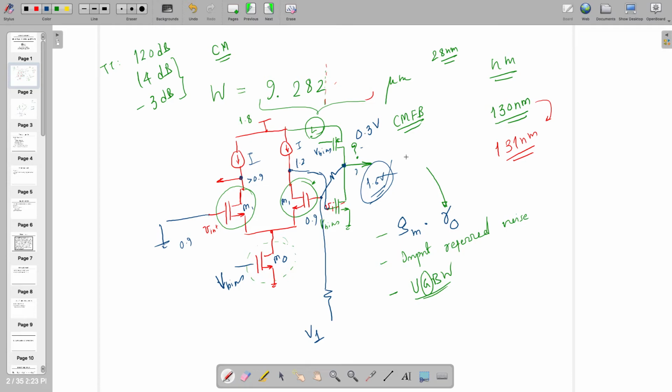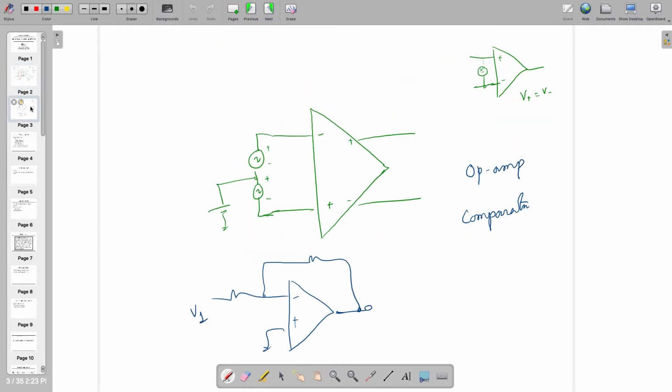If you remember, the worst case condition is the one when there is unity gain feedback. The worst case condition occurs when your system is in feedback. Open loop looks like this one. When you are making it in feedback, if you remember, it was going like this. And in negative feedback, at unity gain, there was one bump over here and coming there. So the worst case condition is the unity gain, so you need to check everything at unity gain. If I want to make it unity gain, what I can do, I'm going to add one inductor over here, and note that this is just for a simulation. Okay, not here.